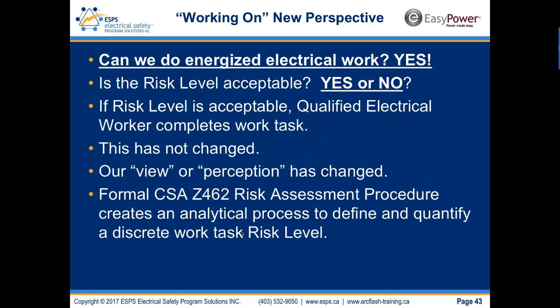So can we do energized electrical work? Yes, we can. Is the risk level acceptable? Yes or no. If the risk level is acceptable, the qualified electrical worker or the qualified person completes the work task. This has not changed, but the risk assessment has, and our viewer perception has changed. So I'm finding in industry that there's a belief that operating energized electrical equipment is an inherent arcing fault probability, and it's not. So we need to manage our perception and our thinking and our understanding of arcing fault and arc flash probability, and use this risk assessment procedure to help us make those decisions that are credible, practical, reasonable.